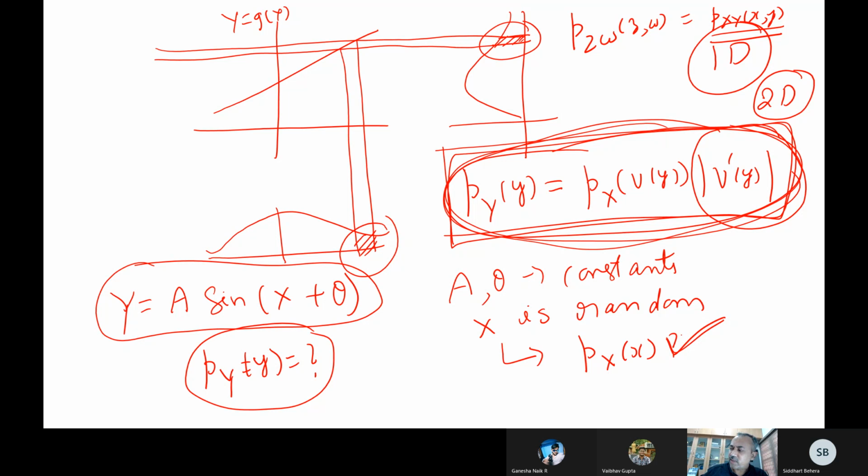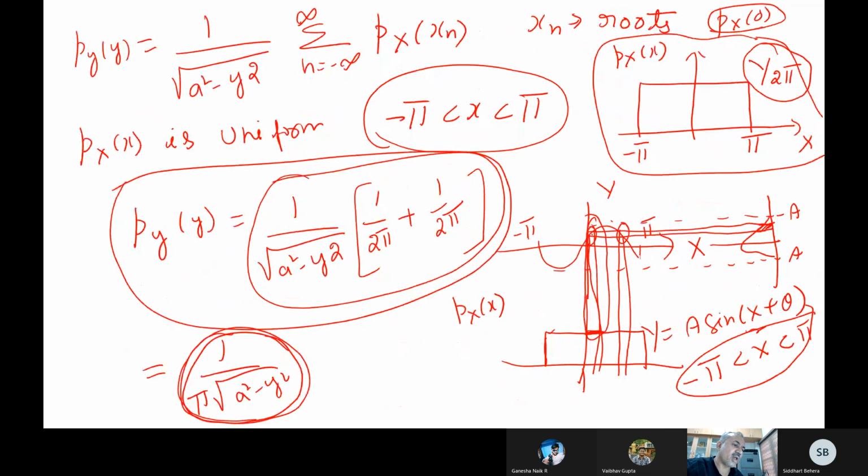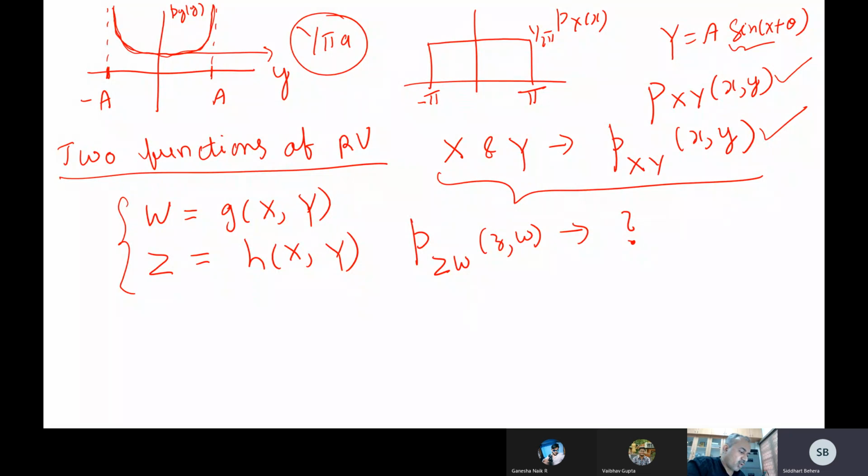What do you call that expression, the derivative in two dimensions, or 3D, 4D, 5D? You use it in FEM everywhere, no? A parent element will be there, like a quadrilateral or whatever. So you have to do a transformation, right? You have seen isoparametric elements and other things. When you do this mapping, you may require the derivative also. What do you call that quantity? What you said is fine, partial derivative only. It is the Jacobian. Jacobian, excellent. So that is the Jacobian.